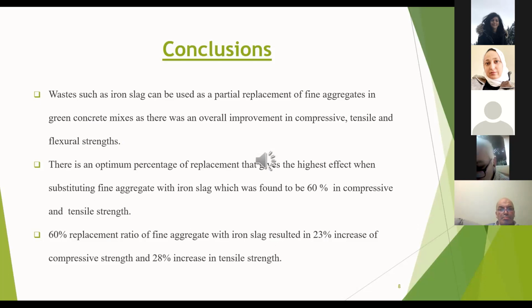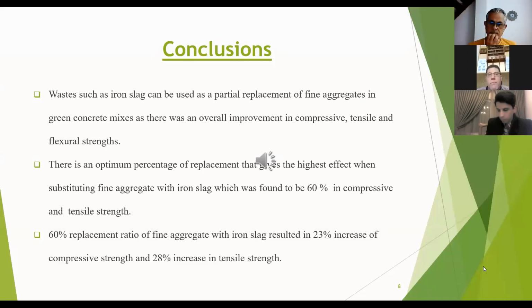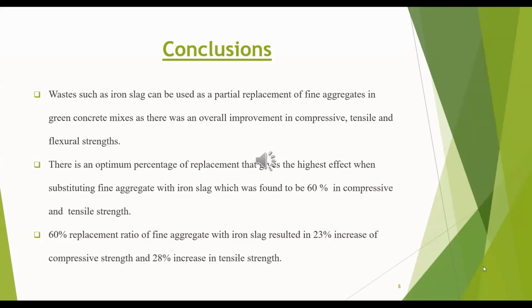Second conclusion, that there is an optimum percentage of replacement that has the highest effect when substituting fine aggregate with iron slag, which was found to be 60% in compressive and tensile strength.